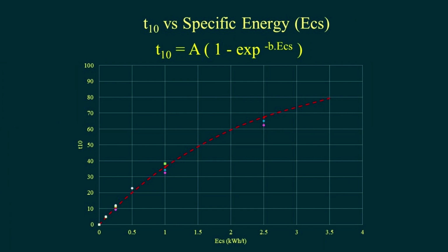And that map sits in JKSimMet. Each size fraction is assigned an energy. The energy goes into that equation. You as the engineer have given it the A and the B. It spits out a T10. And if you remember what I said before, the algorithm works backwards to generate the entire distribution as the appearance function. Very elegant.